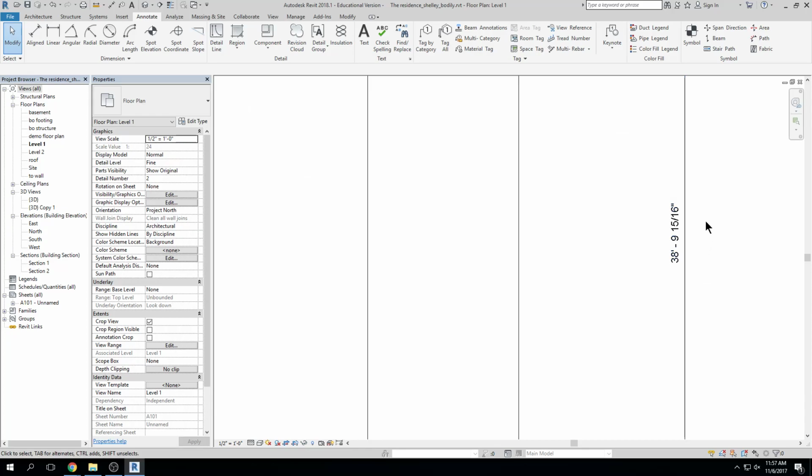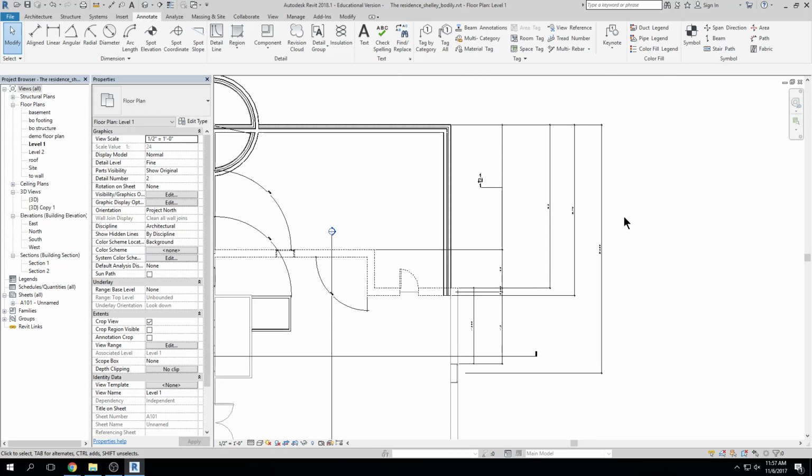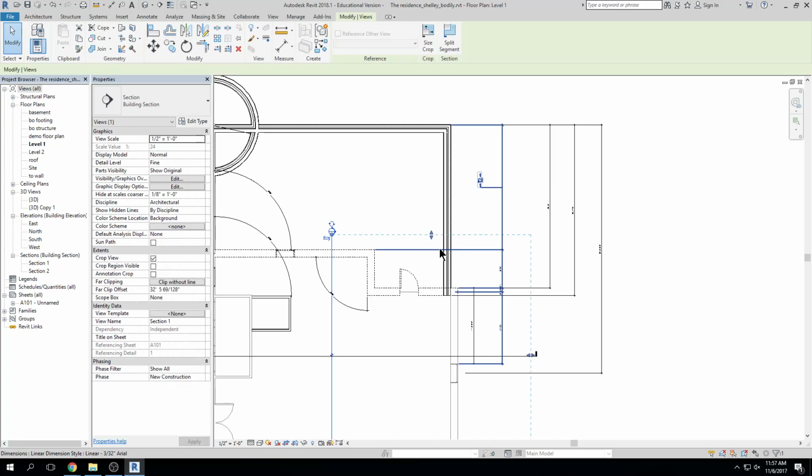Maybe you all don't know, but this text has to be a certain height in order for it to scale down to then print a correct size, okay? I'm not going to get into that explanation, but this is kind of the best part about Revit, where I change scale and it updates all of my annotation, it updates all of my section markers and interior elevation markers and all of my everything, right?